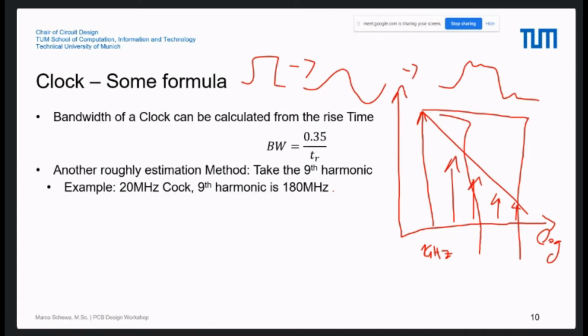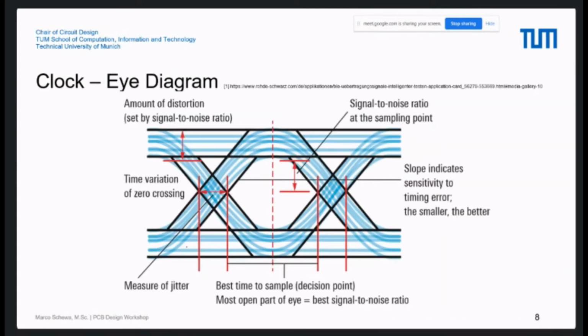So one question was about the jitter. The jitter is, you can also say, the noise of the phase. That means that the phase here is very noisy, so you do not have exactly 50% duty cycle, you have a duty cycle of about 49% to 51%. So at every step it changes a little bit. So therefore you can say it's the noise of the phase or the noise of the duty cycle.